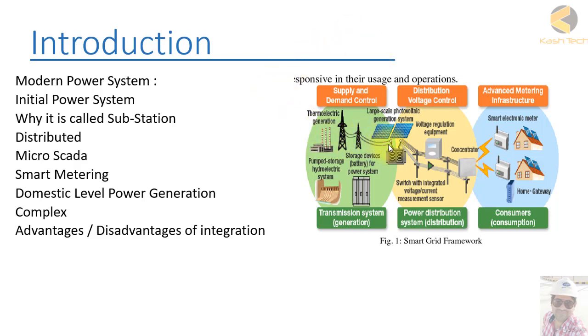Using transmission lines, the power is transmitted to the remote load centers, where again using transformers the voltage is stepped down, for example from 500 to 220 and then 132 kV, and further to the utility distribution voltage of 11 kV. In some countries it is 33 kV. Then it is stepped down to the domestic voltage level of 400 or 110 volts, which differs in different countries. So in this way all the network is connected.